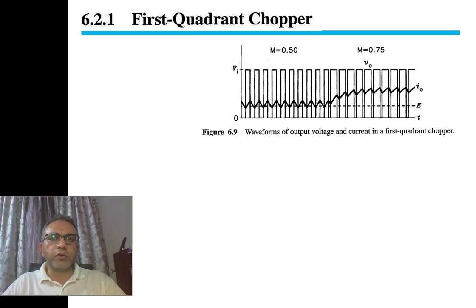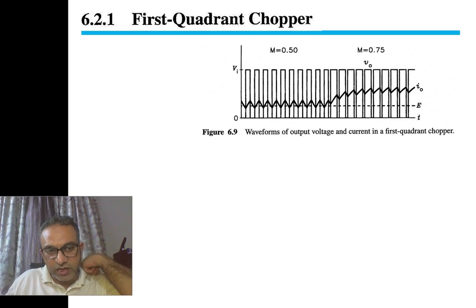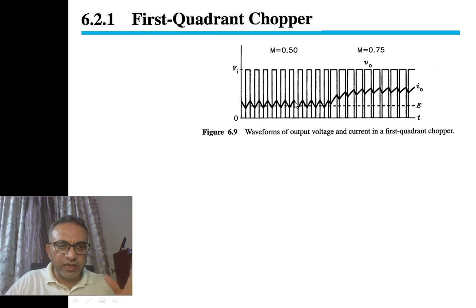Hence the output voltage will be the average, that is just 50% of input voltage. Now it is very interesting to see that we have this triangular waveform. In fact, if we magnify, it is not triangular, it is an exponential function, just as we saw in the previous current equation. And this current, as we saw in the equation, is riding a constant value.